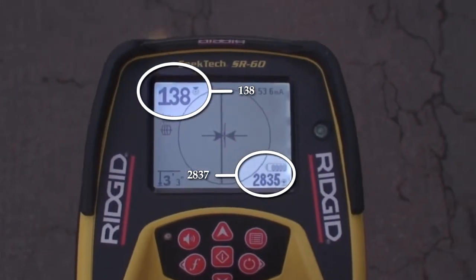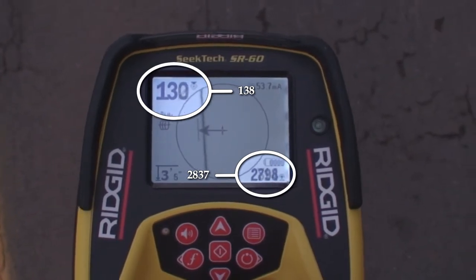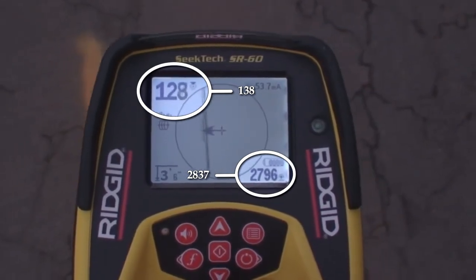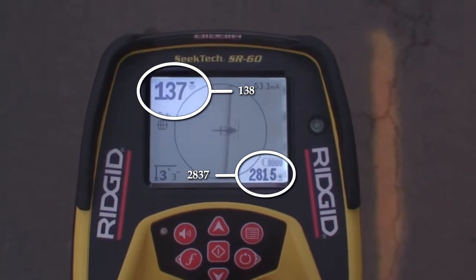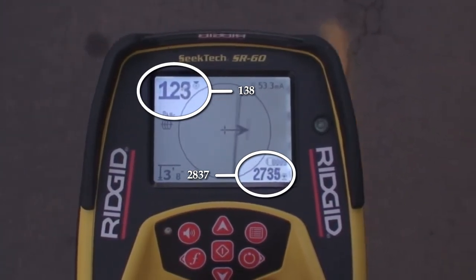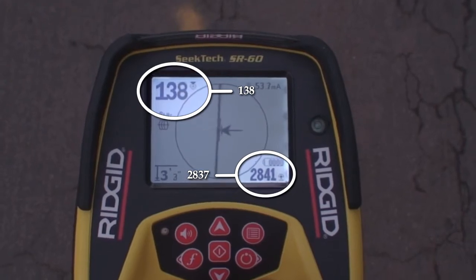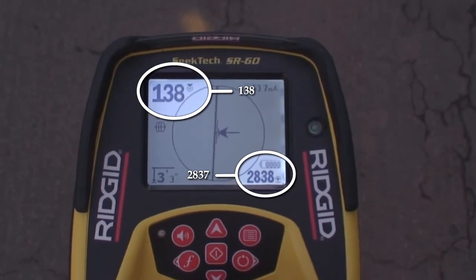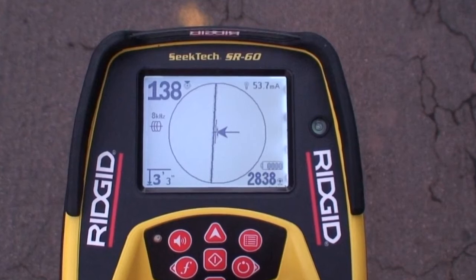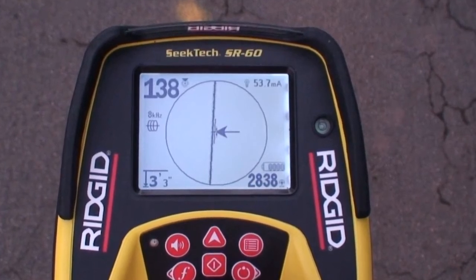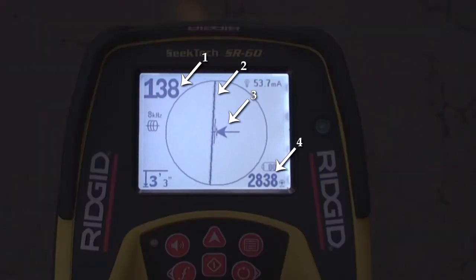Keep an eye on the two signal readings as we move to the right of the mark and then to the left. In this case, both numbers decrease when we move to either side and are highest when we're directly over the mark. Because both numbers are highest at the same point, this means they're both locating the signal source at the same topside position. They're also in agreement with the tracing line and guidance arrows, which means that we have 4 separate elements in agreement with one another. That's a good indication that our signal is trustworthy and not distorted.